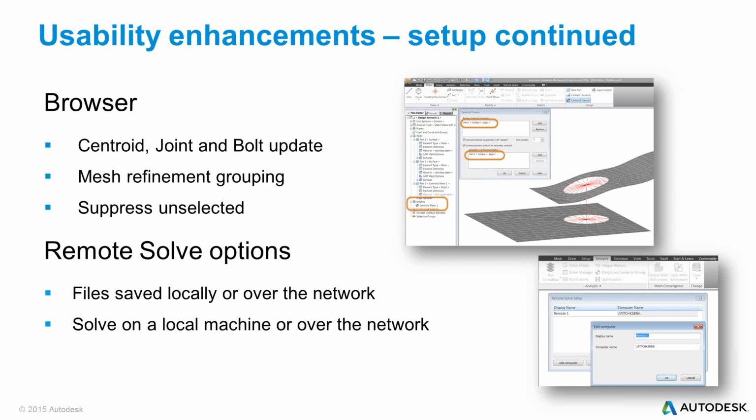The browser has been improved to allow for mesh refinement grouping and suppression of either selected or unselected parts. The 2016 release includes an easy-to-use remote solving option as well. This will allow users to run analyses on remote computers within their network.